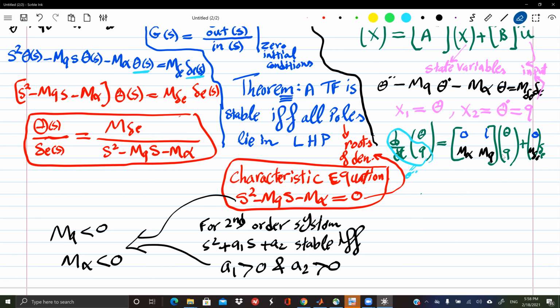So okay, we filled already the second row because this is supposed to be easy or straightforward. Why? Because I'm using my only equation of motion to fill the second row, and I ran out of equations. I had one equation, I used it. What is the first row then? How should I fill it? Actually, you fill it using the definitions of your states.